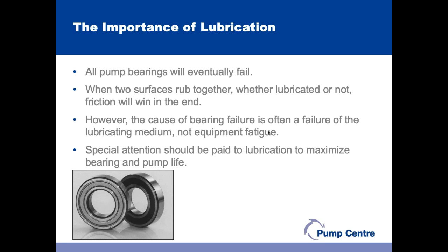But the reality is that in many cases, the reason that bearings fail is not because they've fatigued, it's because the lubrication hasn't been attended to. And it's really important to attend to the lubrication to maximise the bearing life and therefore the life of the pump.